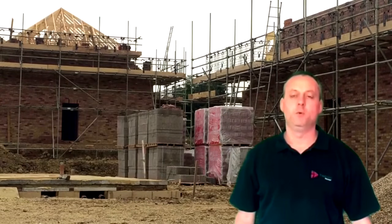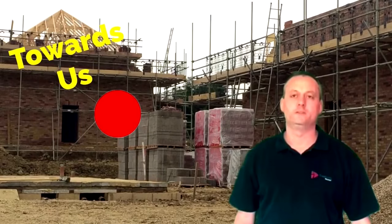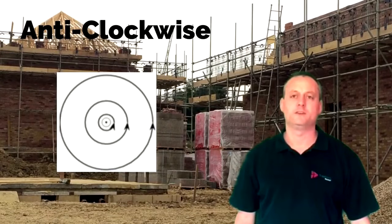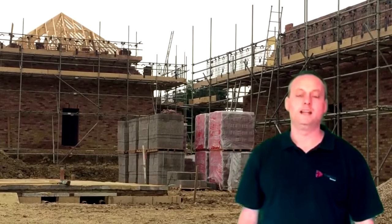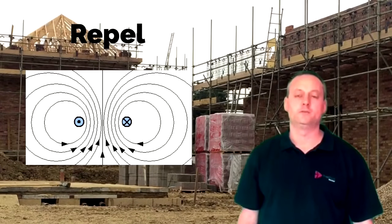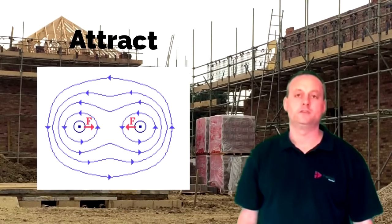Likewise, if the current was coming towards us, or somebody had thrown a dart at us, the first thing coming towards us was a dot or a point, and that was used on a drawing to suggest that the current was coming towards us. Current coming towards us would create a rotating magnetic field around the conductor that goes in an anti-clockwise direction. We then looked at two current carrying conductors placed side by side, carrying current in differing directions: the two conductors would repel or be pushed apart. Where we had two conductors side by side carrying current in the same direction, the two conductors would be pulled together.